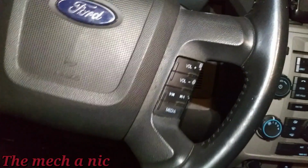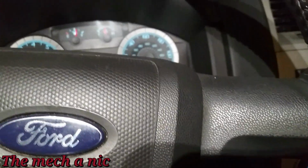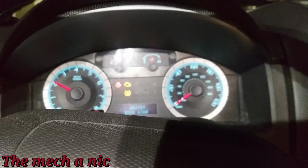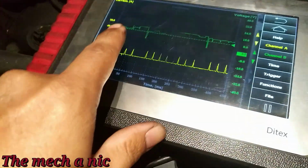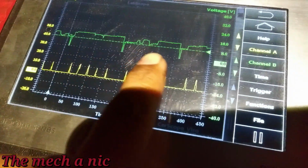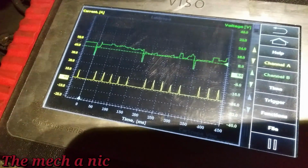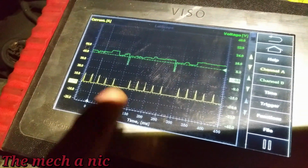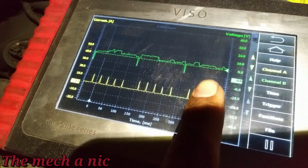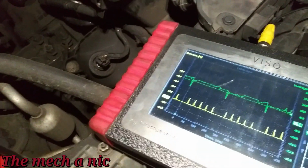I want to help this thing warm up a lot faster, so I'm just going to give it some throttle, nothing crazy. The longer the engine runs, the more and more my second channel is starting to look like the waveform I'm expecting to see. You see, it's starting to resemble that injector turning on and off, little by little. So of course, let's just keep waiting, let it get hot.